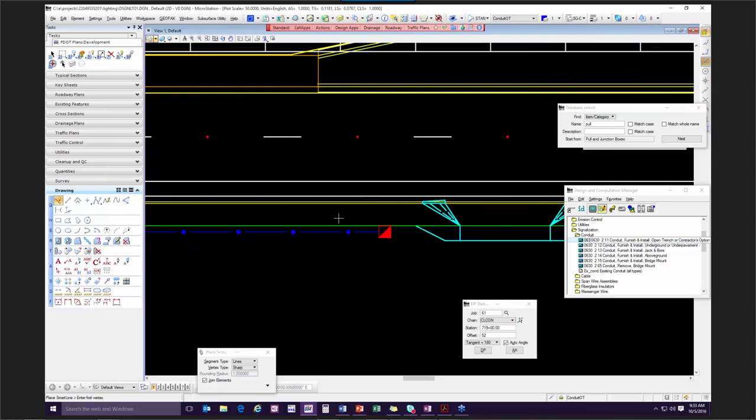So far I've been using open trench. It's out behind the back of a sidewalk. If it's new construction, you may not need this. They may place this before you start constructing the driveway. So it could still possibly be open trench, but if this was an existing driveway that we're just reconstructing, you might have to either jack and bore or directional bore.